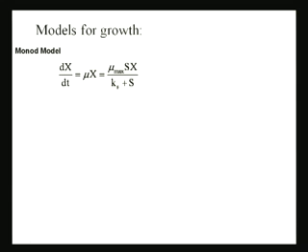Yes, because the batch reactor is the only kind of reactor which is not a continuous reactor. If you have a continuous reactor, then obviously there have to be input and output terms. So dx/dt cannot be written as just a reaction rate. This is something I want you to be very clear about, because I see students keep doing it despite telling them again and again: dx/dt equal to reaction rate only and only for a batch reactor.